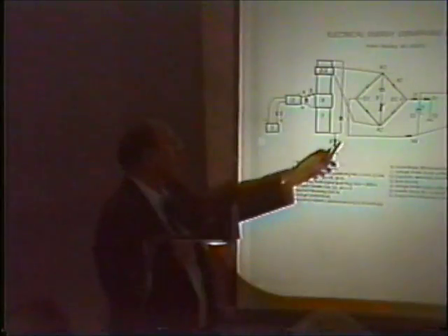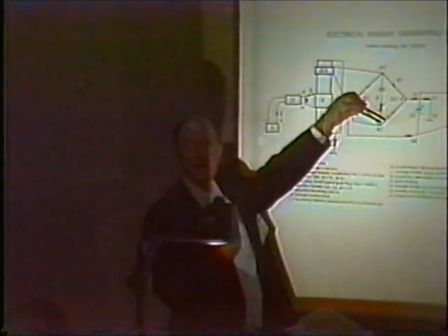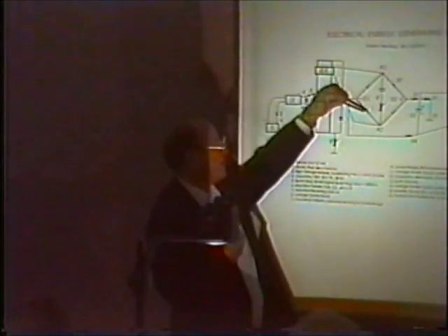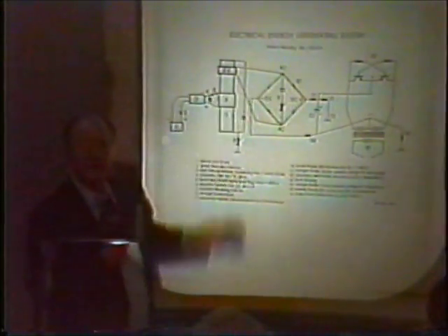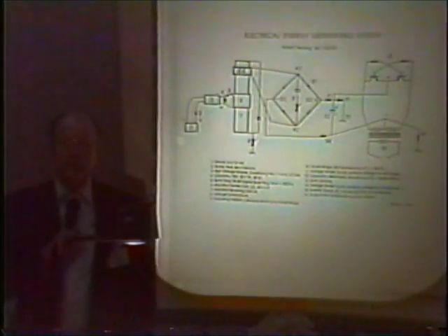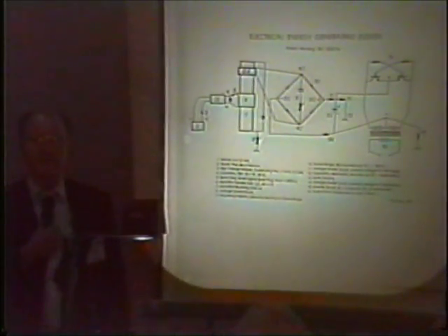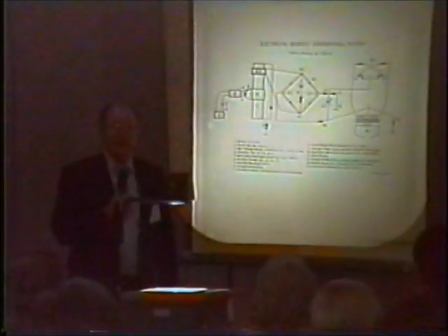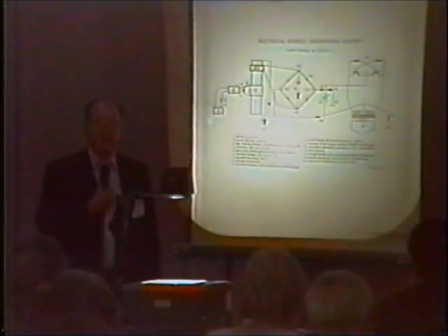Yeah, well, you've got voltage dividers. This is a frequency adjust deal here that if you need it, you may not need it. It depends on the input to the diode bridge. The diodes which I use are high voltage radio frequency diodes which show up in your television sets and things like that. They start at about 25,000 volts and go up, and 100,000 is not uncommon.